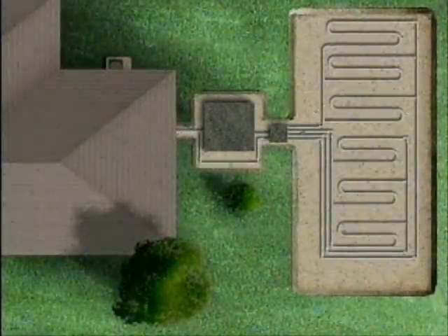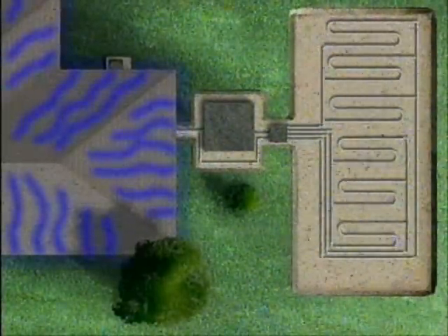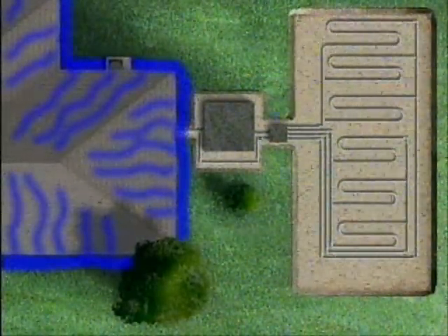Placement is equally important. The drip field is designed to treat wastewater, not rainwater. Rainwater coming from driveways, roofs, and other impermeable surfaces upslope from a field should be diverted. A field flooded with rainwater has little capacity for managing wastewater.